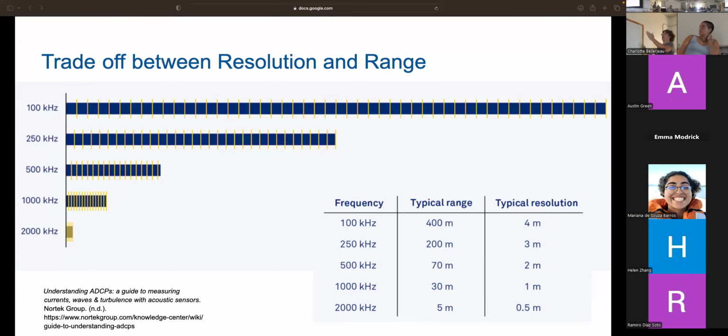and basically how far this code picks up in the water itself, because once that reflects off the stuff in the water, we have to come back and actually compare that to the signal itself. We call this the covariance method. Basically, we take this and compare it to what we know it should be, and that's how we actually get the Doppler shift, because as this comes back, the frequency will be a little bit different. When you take the FFT of that, you'll see peaks at a certain frequency, and that will just shift around a little bit.